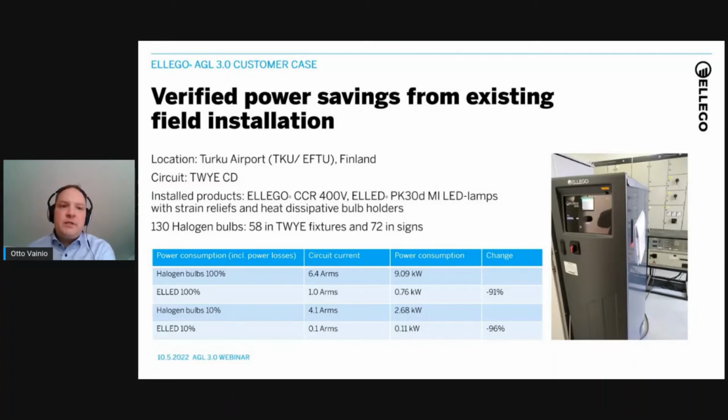Then, of course, for any given circuit, it depends on the usage cases. It depends on the actual required power and the levels, what current levels are used. In this case, and this is by far not an extreme case, even in this case, there's a lot of power losses within the cables with these standards from 2.8 to 6.6 amp current. Everybody knows it's current squared, the power losses within a resistive device such as the cabling.